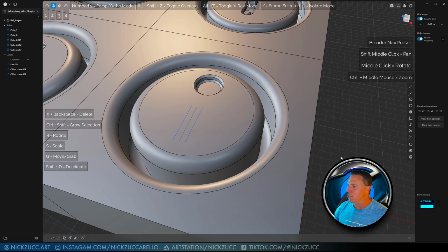All right. Next thing we're going to do is go to this area that we've got right here for the circle tools. If we click and drag out, we can do a tangent arc right here like this. This will allow us to snap to this endpoint and then come here and snap to this point right here. And I can go ahead and right click and confirm that.